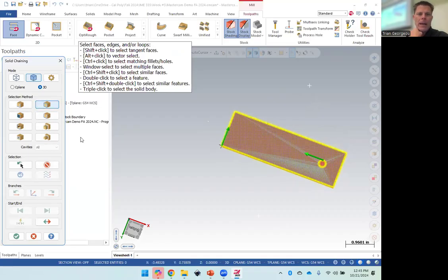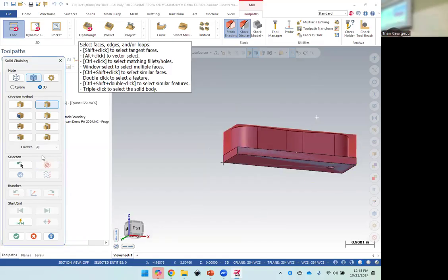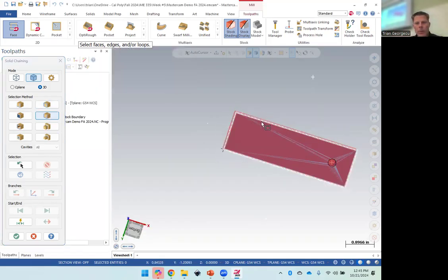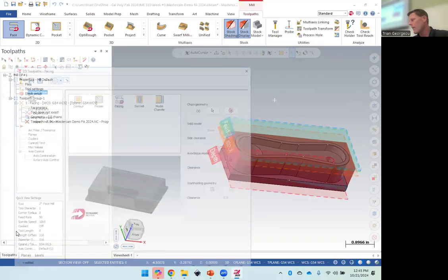Click off it, you hit the little red X. That'll just do the outside if you don't pick the entire face. See, so it loops the entire outside. Then I'm going to press X again. And what I'm going to do at this point is show you the partial. So the partial will also loop it. So there's many different ways. You just got to play around with it. Cool. At this point, I'm happy with my selection. So I'm going to hit the check mark.